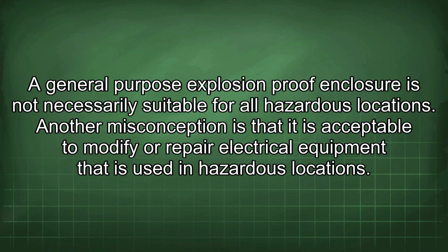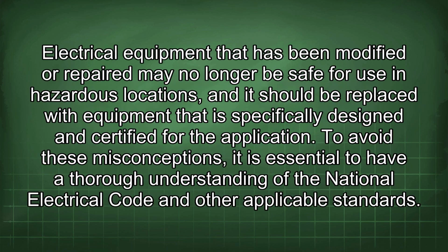Another misconception is that it is acceptable to modify or repair electrical equipment that is used in hazardous locations. Electrical equipment that has been modified or repaired may no longer be safe for use in hazardous locations, and it should be replaced with equipment that is specifically designed and certified for the application.